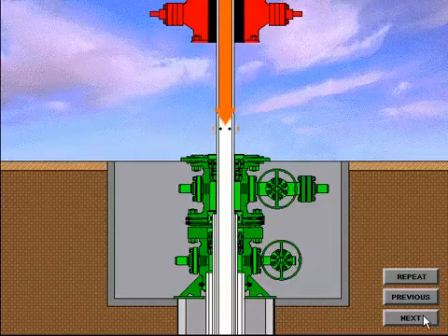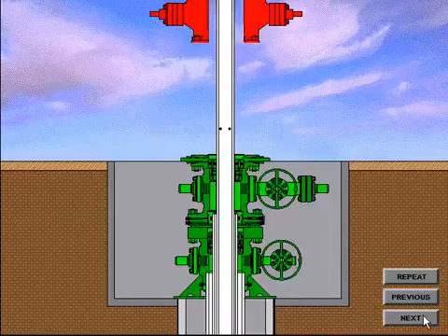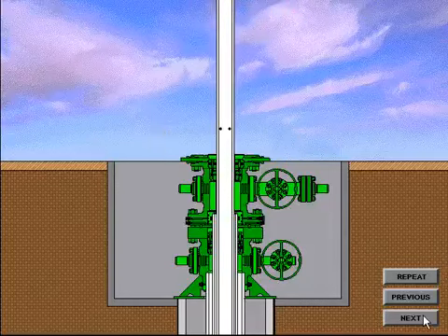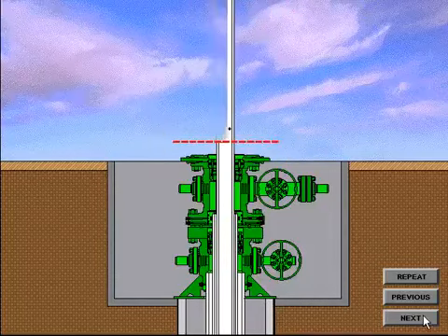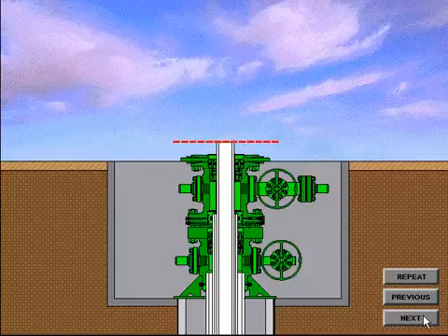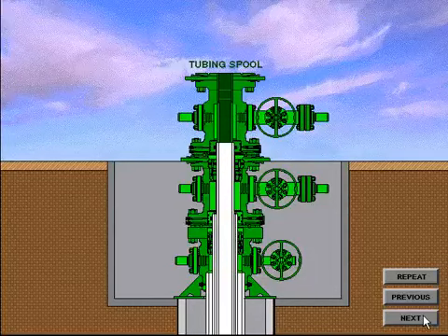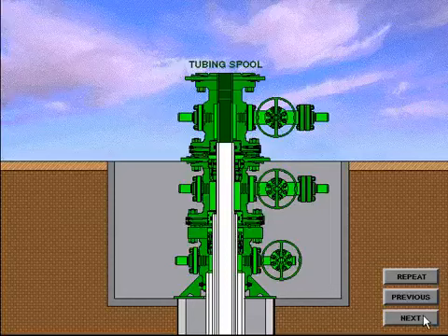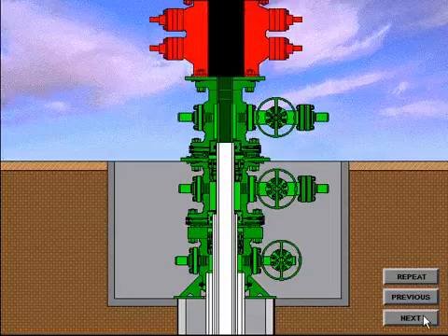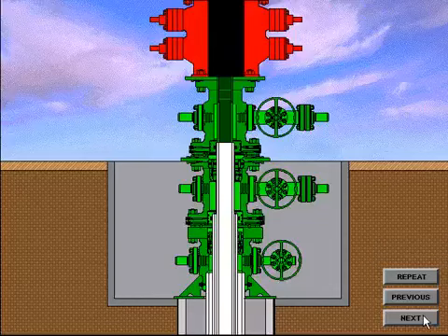The casing riser is drained, a rough cut is made, and the BOP system removed. The final cut is made to the production casing in preparation for installation of the tubing spool. The tubing spool with a crossover seal is installed in the same manner as the casing spool. After the tubing spool has been installed, the seals and connection are tested, and the BOP system is nippled up.